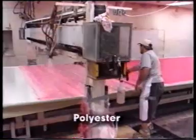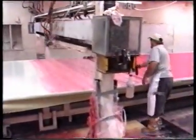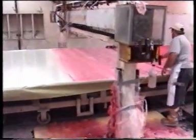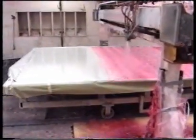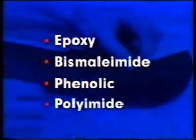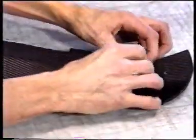The polyester matrix materials are the least strong and the least heat and weather resistant. Within these limits, however, they can be quite versatile. They are also the least costly, thus are used extensively in commercial applications. The epoxy, bismaleimide, phenolic, and polyimide composites provide superior mechanical performance and heat resistance.